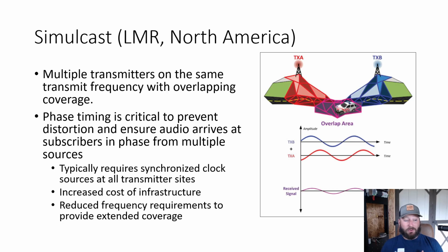Today, there's a way to do it to where you don't have to do it over a clock at each site using a protocol called PTP, Precision Time Protocol. But to the best of my knowledge, in April of 2026, there is not a manufacturer of a simulcast solution that is currently using PTP across your links. There may be a manufacturer that is using PTP from the site clock to the equipment itself, but not across the master link. So of course, because you have more equipment, this has an increased cost for the infrastructure, and